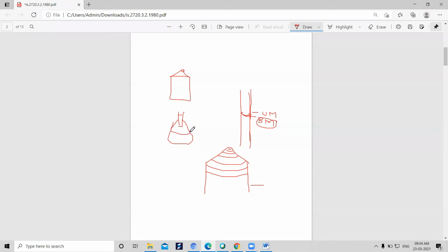In the same case over here, what is the meniscus like? It is always there. But when I move to the V shape, the inverted V, the meniscus becomes zero. So this is for the meniscus correction. Why are these shapes like this? Clear? For the air vent, an air gap is left here. No issues with it. This applies to both the density bottle and the pycnometer.